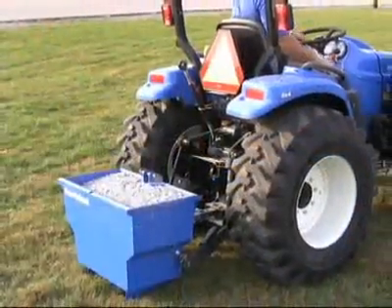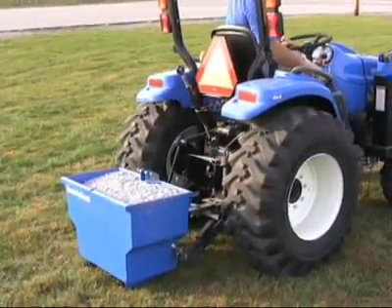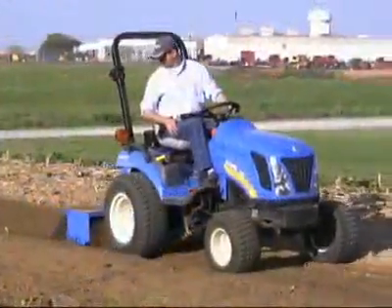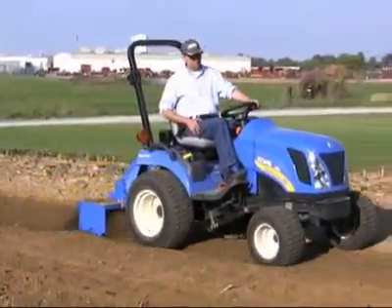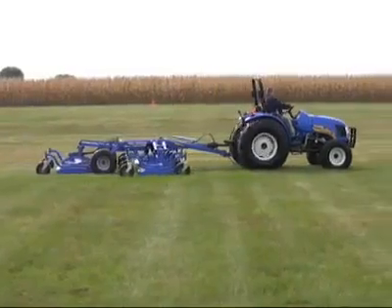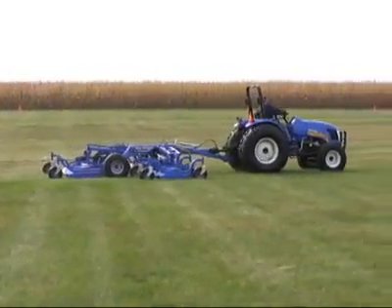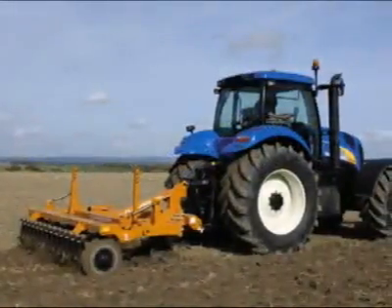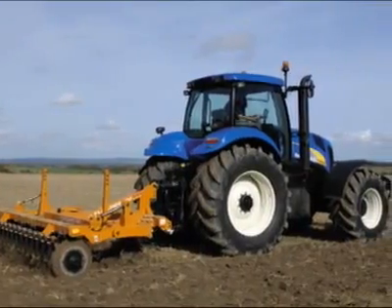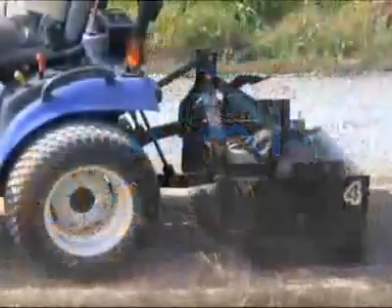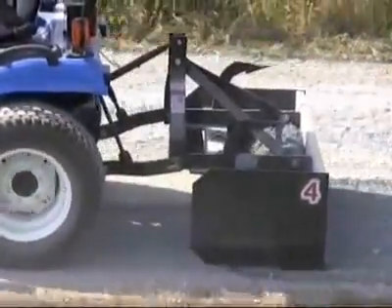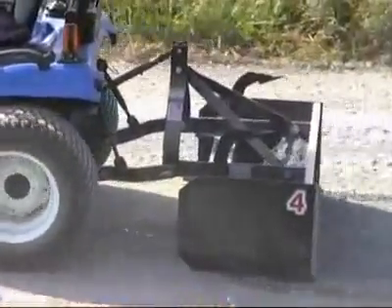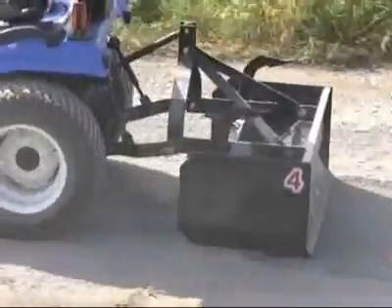Now, there are several different hitch sizes, or categories. These categories, numbered 1 to 4, refer to the size, dimension, and strength of the hitch. The higher the category, the more lift capacity the 3-point hitch has. Therefore, Category 4 3-point hitches are on the largest agricultural tractors. New Holland compact tractors are built with Category 1 and 2 hitches to provide you with fantastic lifting capacity for rear-mounted implements. That's it, front to back, top to bottom.